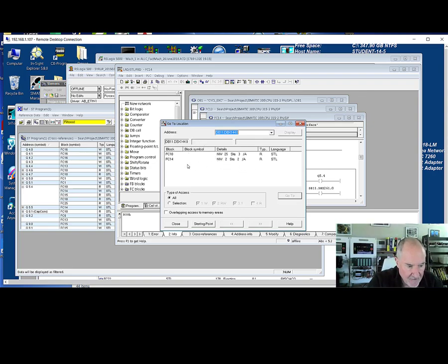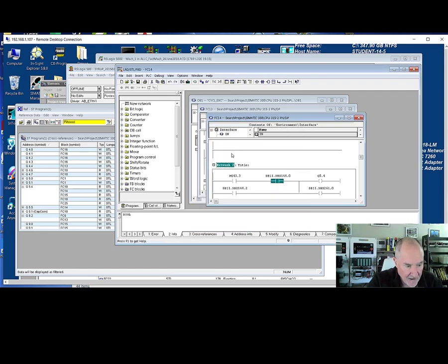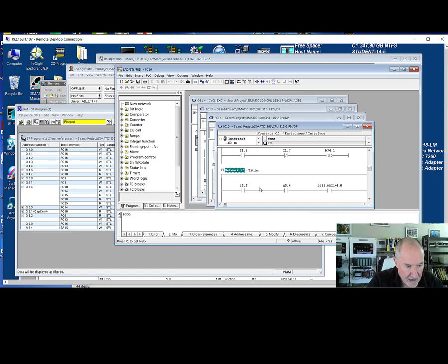And you can see here the only places where that is are read only, right? So they are reset. And we'll go to one just for fun here. Since they're in a different routine, it opened it up here. And you can see this data block, only the bit itself is showing here, not what actually changed it. So the thing that I would want is the write bit, the thing that actually changes that bit.